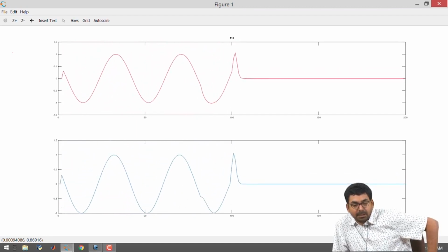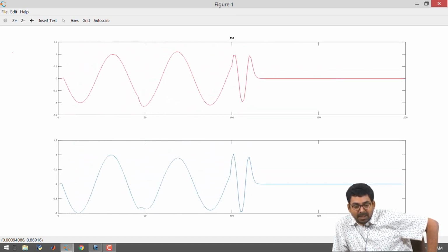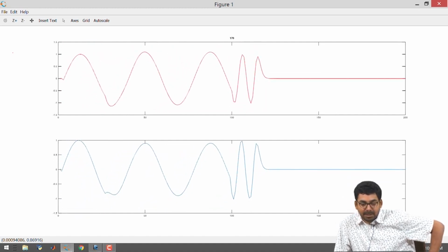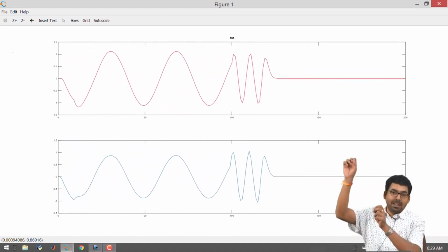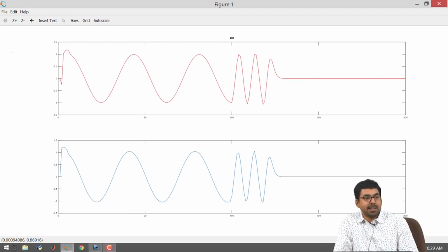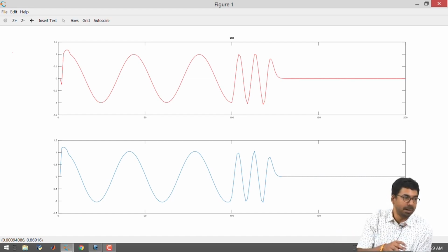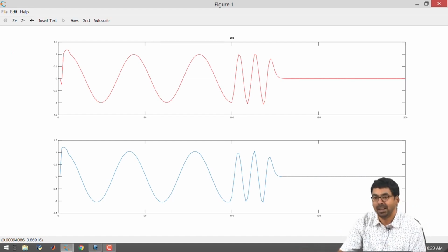There is a bigger reflection happening. Your wave is traveling far too slow in the second medium, and it seems to have some distortion in the way it is represented. It does not look like a full sinusoid, it looks like some points. There are sharp points in your sinusoid. That tells you about the way you are sampling your sinusoid in the second medium. As you change the medium, or the characteristic impedance, from one to another, the way you sample your sinusoid will change. Those are minor details, but L and C in the right hand section above 1 will work for the simulation condition we have chosen. Anything below 1 will give you an out of bounds error.